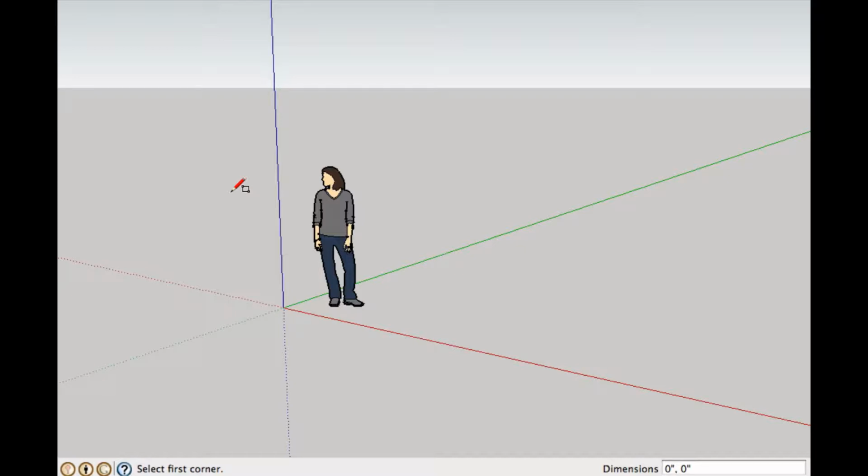You could do this at a number of different scales. You could get an image of that on a scanner and import it into SketchUp and just place it flat on the ground here, and then draw over it. That's actually very easy to do, and once that image is within SketchUp, you can scale it so that its dimensions are accurate within SketchUp. So if you have a wall that is say 40 feet long on that image, you can scale that image so that 40 feet represents 40 feet in SketchUp.